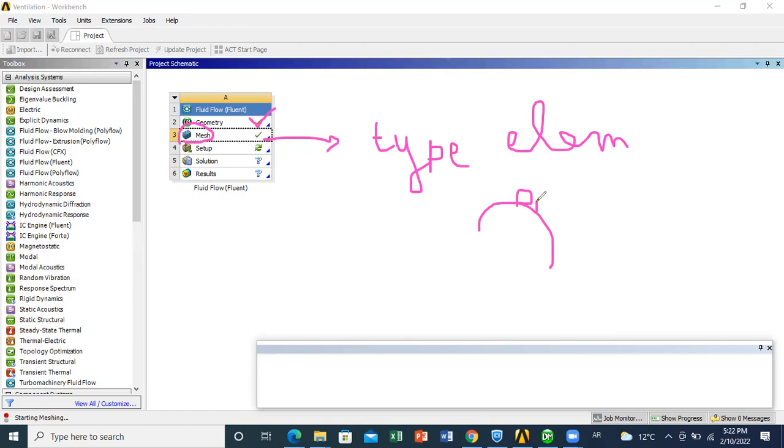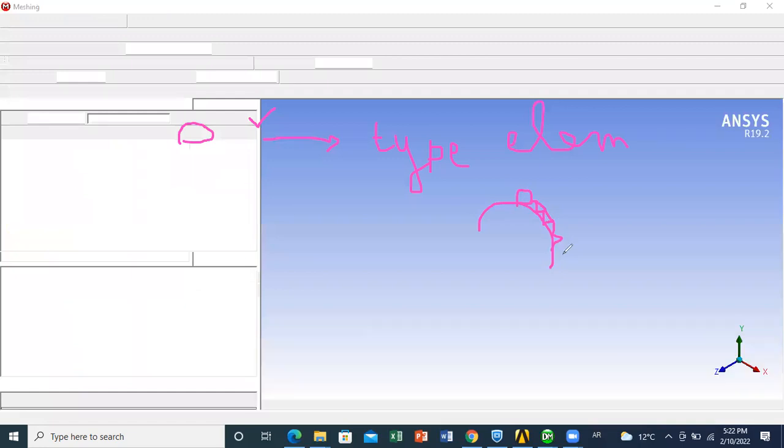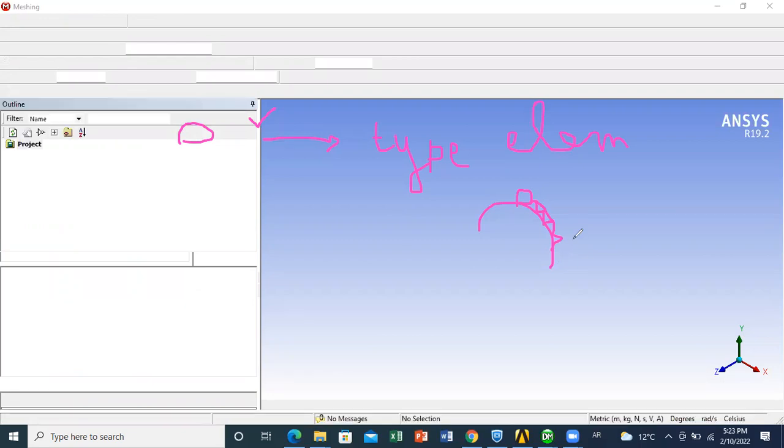However, tetrahedral elements are more flexible. As you can see here, they will allow you to capture the curvature in a good way. And the smaller the size of the elements you use, the better. So you can trap, if you want, finer zones, and then have better computation. One of the best strategies to enhance the mesh quality is to reduce the face size.